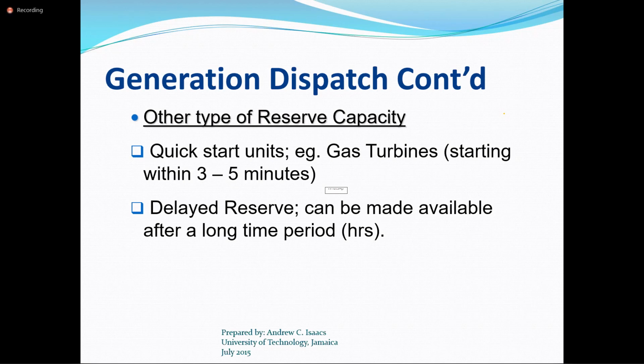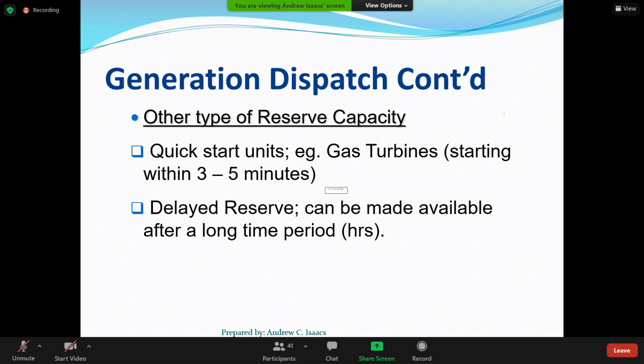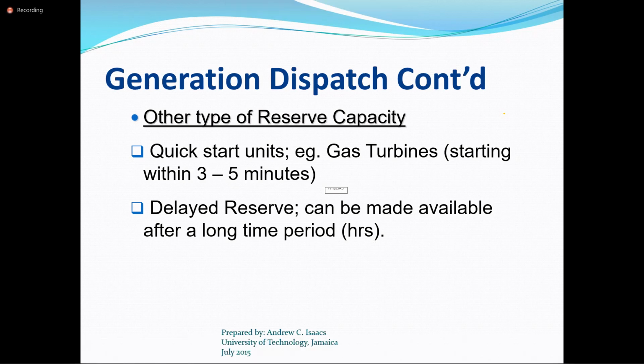Yes. And so if you go to system control, you would see these guys who, if you don't know better, you think they are just having fun, sitting down looking at these big screens. Part of the idea is that they must be monitoring what the load is like on the system and what the generation is like. They will make the necessary communication with a particular plant manager or the operators to start getting units online. So there is constant monitoring of the system to ensure that the balance is maintained.